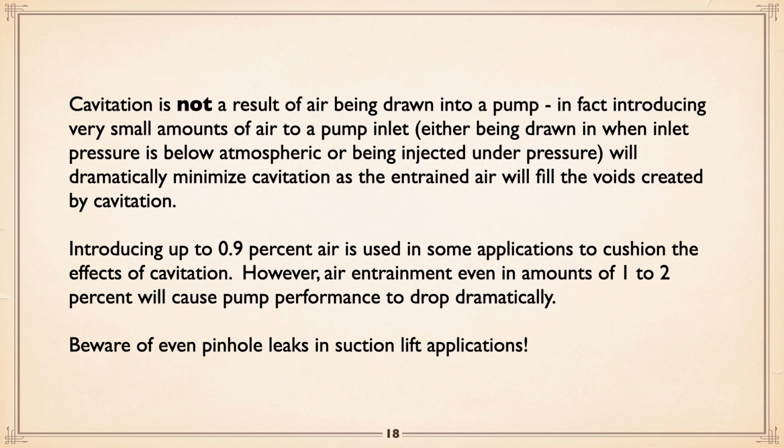In fact, introducing a small amount of air to the pump inlet, either being drawn in when inlet pressure is atmospheric, or injected, will dramatically minimize cavitation, as that air will fill the voids created by cavitation once you've got aerated water. Up to about 0.9% air can be used in some applications to eliminate the effects of cavitation.